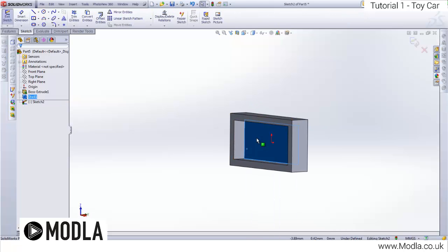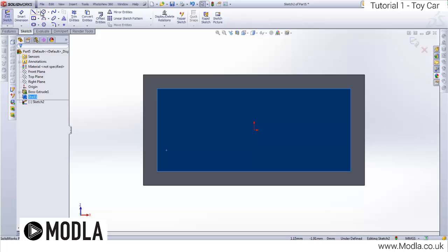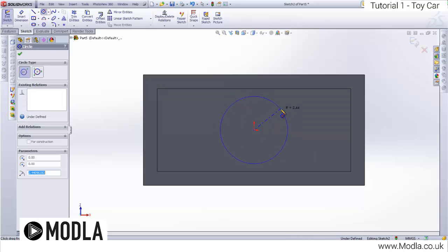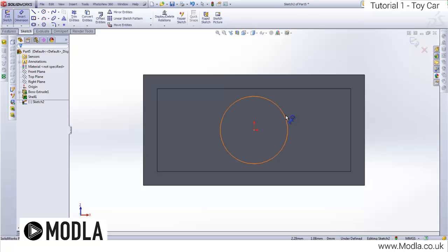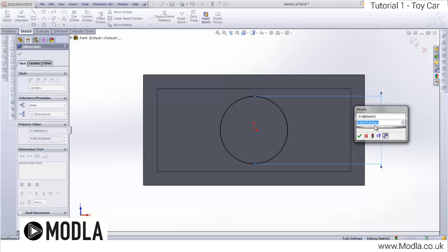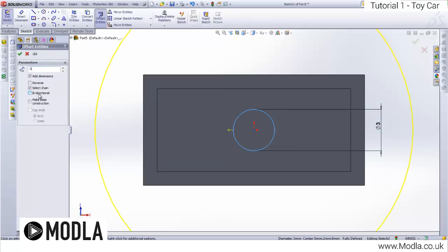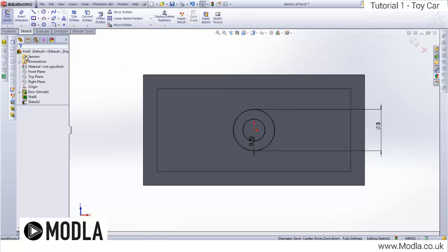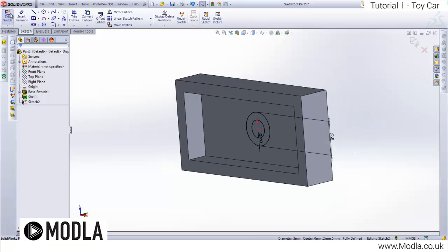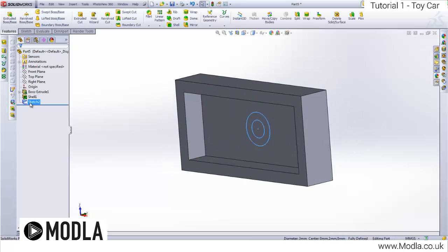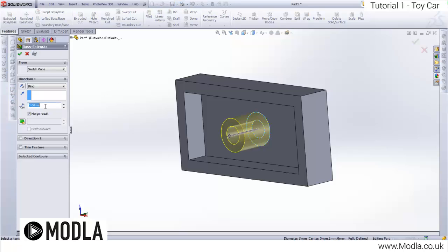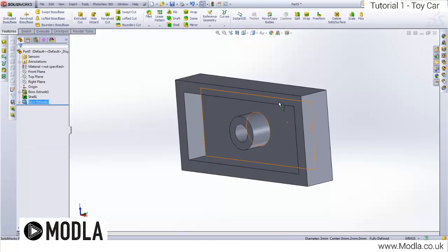Right click, sketch, click on the spacebar, go normal to. It's a bit different in size this time, so we're going to click out here and input a distance there of 3mm. So 3. And then we're going to offset that distance, this time by 0.7. We'll reverse it so it's inside, and there we go. Now we're ready to extrude that. So exit out of my sketch. If I keep my sketch selected, I can go extrude, and this time it's 2mm. Green tick that. Okay, great.